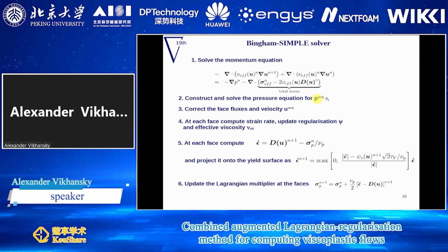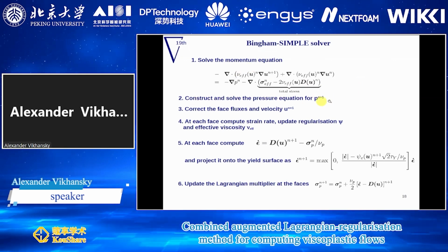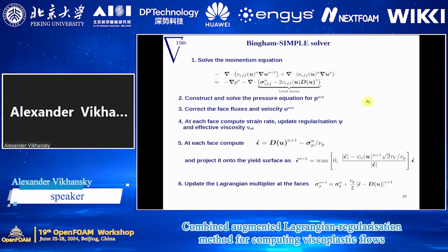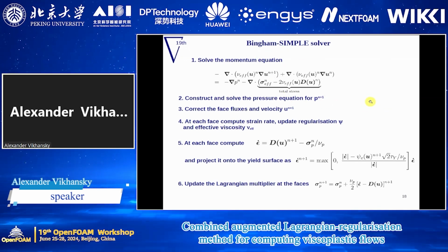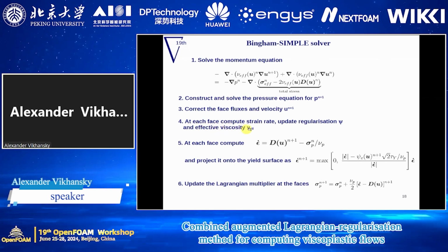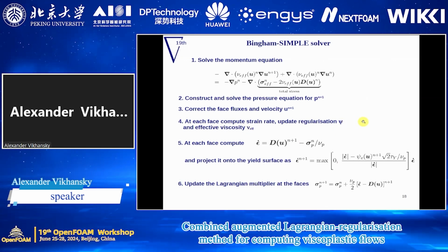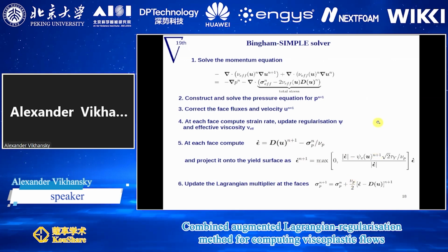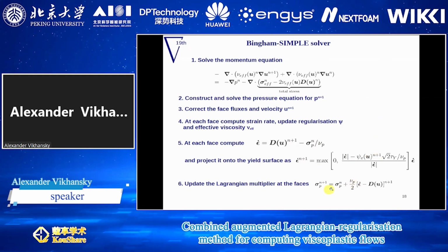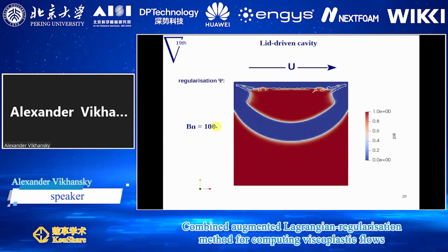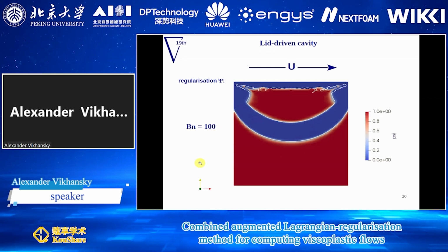So I solve this equation, I make the pressure correction as in the SIMPLE algorithm, and then I calculate everything at the face, effective viscosity, regularization, and so on and so on. Then I perform my rheology calculations to get the new value of stress. And probably, okay, let me go to the demonstration of the results.